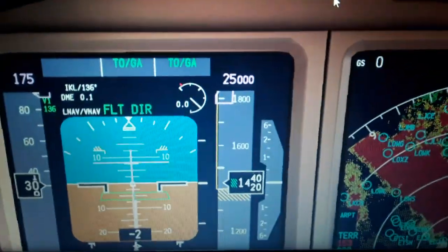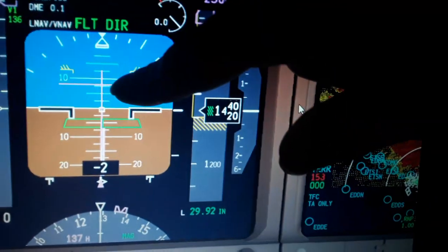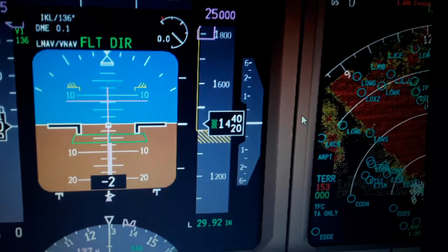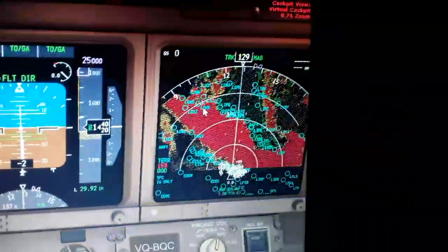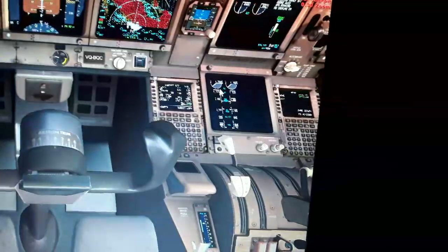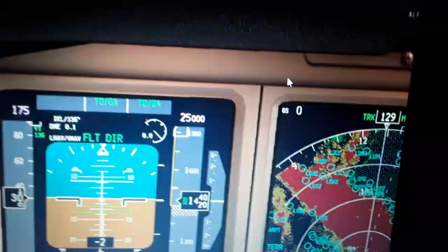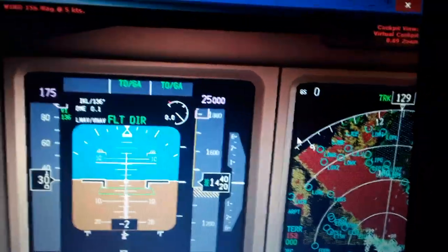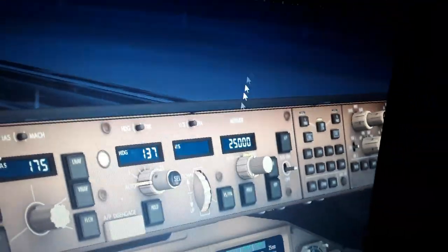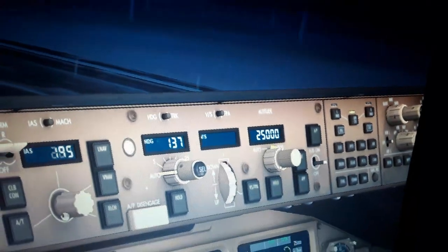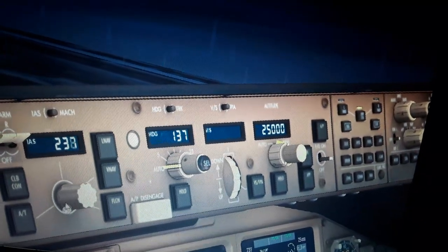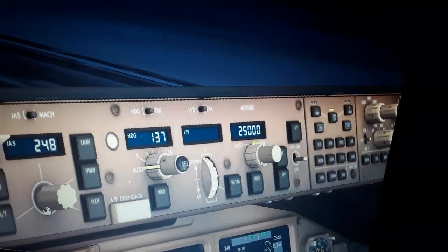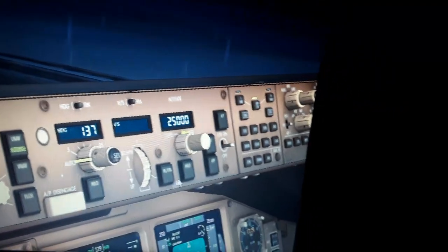You can see the flight director, we have the ILS on, the needle, and we have the mode for takeoff pitch, like 8 degrees. We need to pitch up to avoid a tail strike, only 8 degrees, with the control column. We need not to pitch up too much for this takeoff. So we have the ILS here, the radio altitude, the airspeed selected, and the altitude selected from the autopilot panel. We're going to use a bit more airspeed, and the heading of the runway. You also may use the LNAV along with the altitude hold. The autopilot is off.